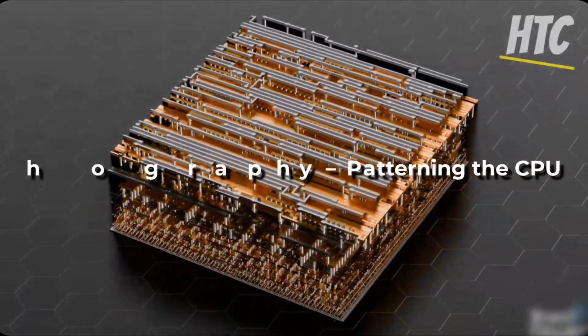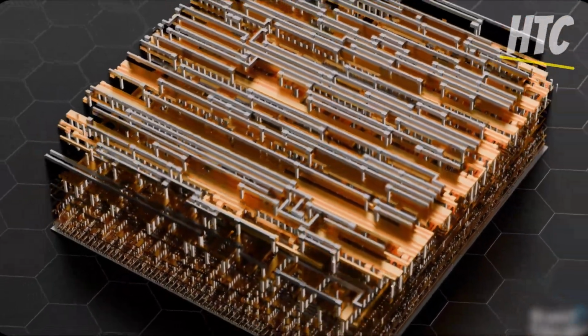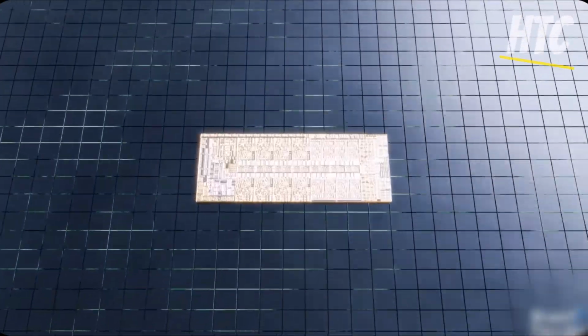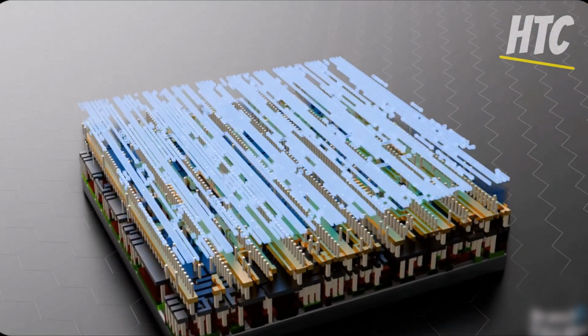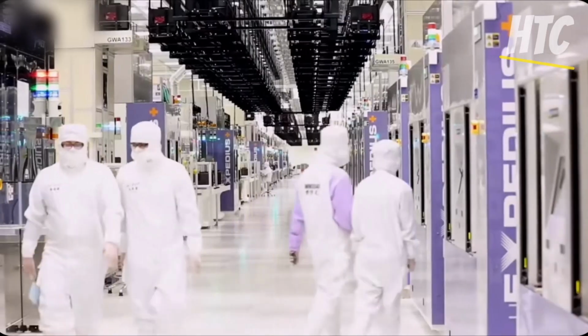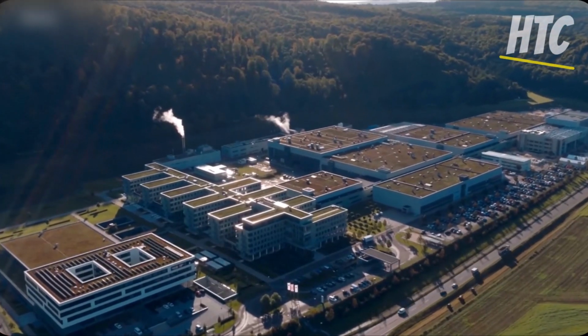Section 4. Photolithography, patterning the CPU. Next, we bring the design down to the micro scale through photolithography, the process responsible for printing the CPU's intricate patterns onto the wafer. The wafer is first coated with a light-sensitive material known as photoresist. Ultraviolet light is then directed through our photomask to expose selected areas on the wafer.